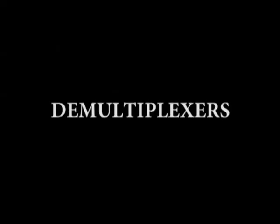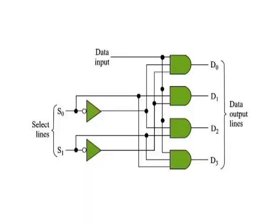Demultiplexers. A demultiplexer basically reverses the multiplexing function. It takes digital information from one line and distributes it to a given number of output lines. For this reason, the demultiplexer is also known as a data distributor, and you will learn that decoders can also be used as demultiplexers. Figure here shows a 1-line to 4-line demultiplexer circuit.